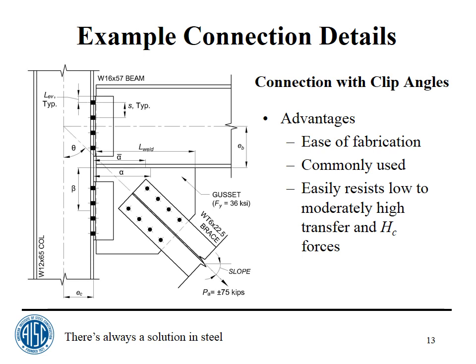Ease of fabrication, that is to explain that. The beam is basically cut short or a little bit shorter than it needs to be. There's usually a setback or a proud dimension here of about a half an inch. So if the beam is a little bit long or a little bit short, that could be made up simply by placing the angles on the beam and on the gusset where they need to be, such that the out-to-out dimension of the fabricated piece is correct.